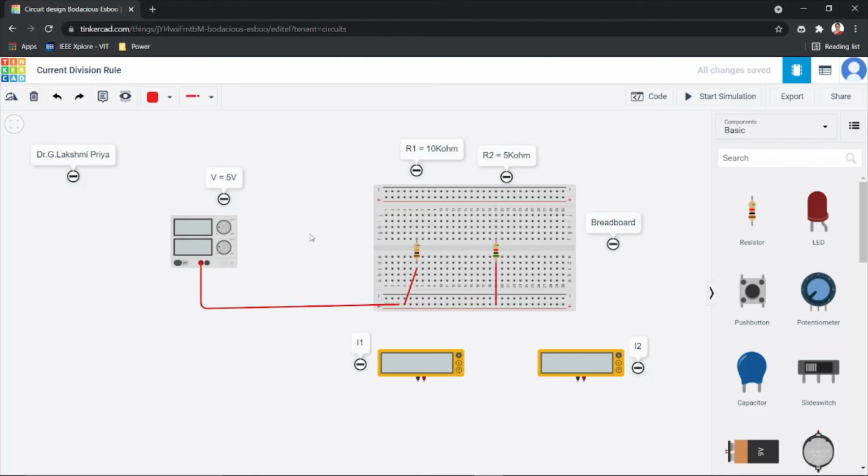So now the other end of the terminal with which we are going to measure actually what is the current across this resistor. So all these F to J are at same point. Now they are all shorted. So I can just take from anywhere the connections actually. So I just bring it here. I just connect it to, yeah, it will automatically pass there. From there again, you need to just take one more wiring and just give a bend here. Just click on the mouse, connect it to the positive terminal of your multimeter.